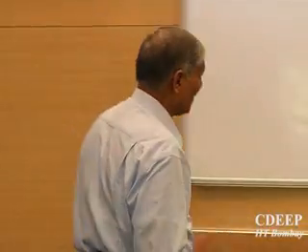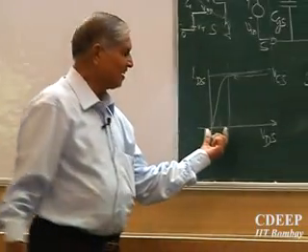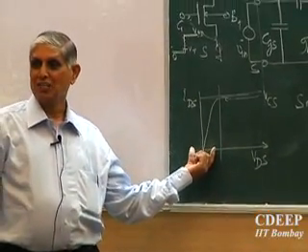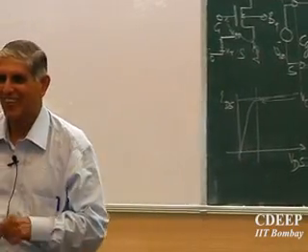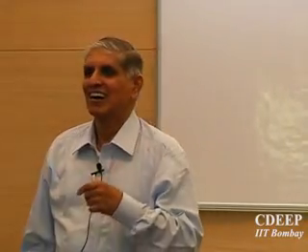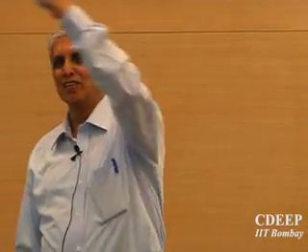But there the word saturation is not used the same way. There the saturation has some other meaning. In fact, now you have said it, here it is called linear region, in BJT it is called saturation region. Okay. So don't get confused now. So right now keep BJT away. So in a MOSFET, when the current actually saturates, we say it's a saturated region.